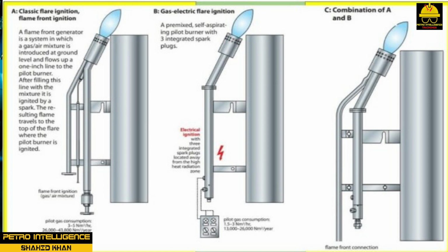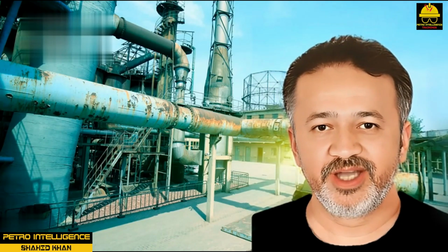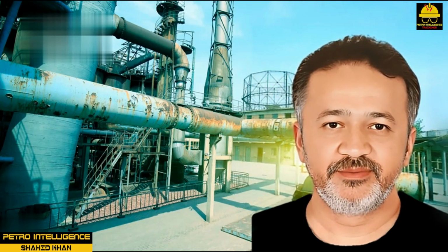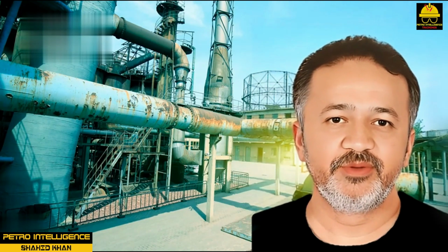The steam flow to the flare is automatically controlled on the basis of the flow rate of gas to the flare. The flare pilots operate on natural gas and air ignited by a flame front generator. Because of the heat radiation from the flare during peak loads, the flame front generator controls are shielded and located away from the base of the flare stack. Entry into the high flare radiation area must be by permit only and must be coordinated with the operations department. Anyone in the area must be in constant radio contact with the control room.